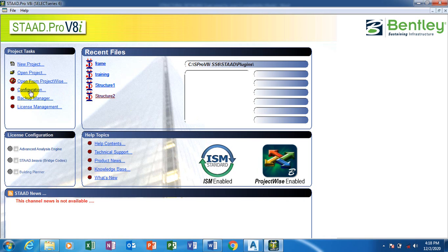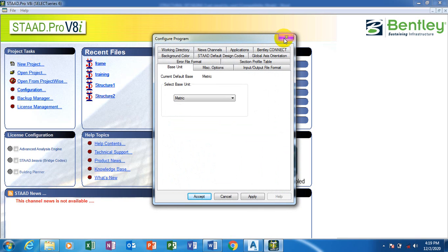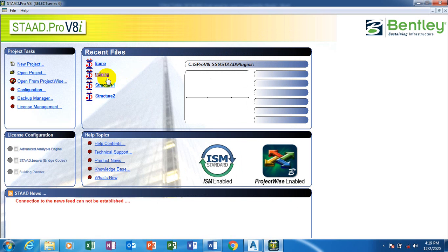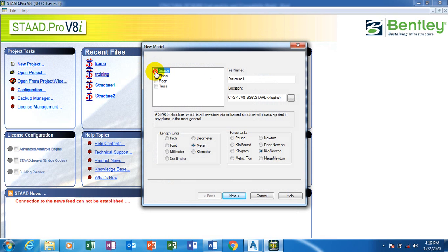First of all, you must configure where you do your settings for the code of practice, the unit of measurement, and the unit of your forces. All of those settings you do from your configuration here, which I covered in the introduction part of this training in episode 1. So when I click on a new project, like I told you, STAAD means structural analysis and design, and the Pro is program.